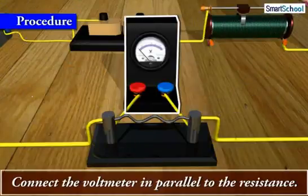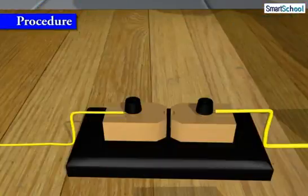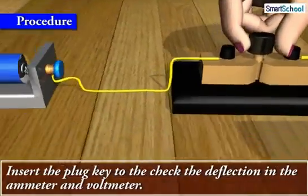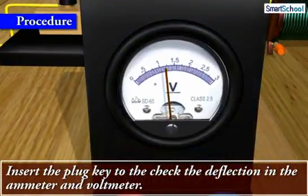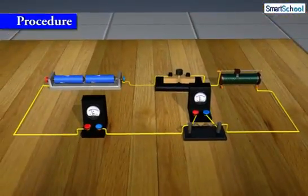Now, connect the voltmeter in parallel to the resistance. Now insert the plug key to check the deflection in the ammeter and voltmeter. This shows that our circuit is correctly connected.